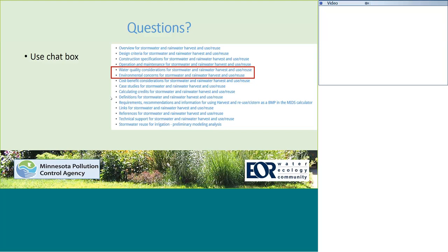So it's always a piece I think could use more review: if you applied in certain soil conditions, if you have a sandier soil, potentially you could apply twice the rates that you minimally need for irrigation, but the plants won't be harmed, and in essence, some of that water might start going down the soil profile and becoming recharge, which again is fine for our purposes, as stormwater is your main goal. If you're out in the arid Southwest and you're trying to hoard water and you want to use it very sparingly, then you probably would use a different approach than we are here. So there are some regional differences too around the country, around North America. But in terms of actual groundwater recharge, potentially piping down, that is not discussed at all in the manual. I just looked back at the overview.